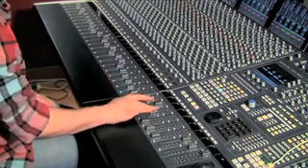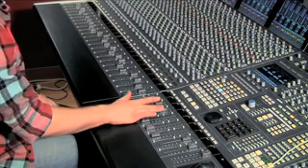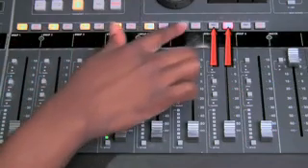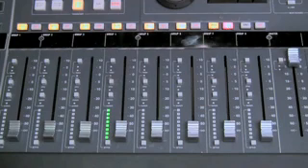So that's all our piano and organ channels controlled as one. Above each fader you have a solo and cut switch, and again, these solos and cuts will affect whatever channels are assigned to that group. Beside the VCA group faders, you have a master fader, and this master fader can be assigned to control mix bus A, mix bus B, or mix bus C.